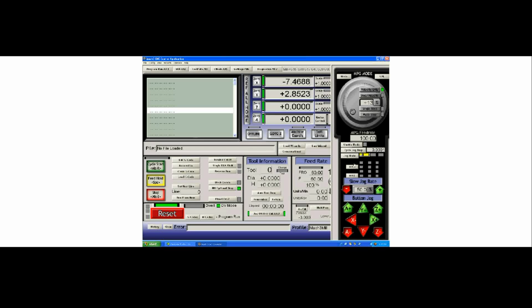Notice when I press the shift key that the fast jog indicator lights up. Otherwise, you're on normal speed. The rest of the controls on this page you can pretty much ignore until you get more advanced. We have settings for the slow jog rate. You can increase it. You have buttons which will allow you to jog simply by pressing the button on the screen here. When it comes to the MPG modes and shuttle modes, leave them off for now unless you get to the point where you're hooking up an MPG.